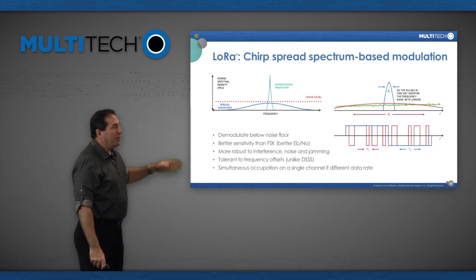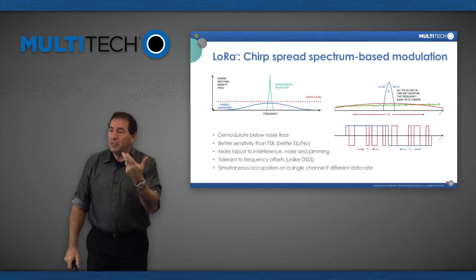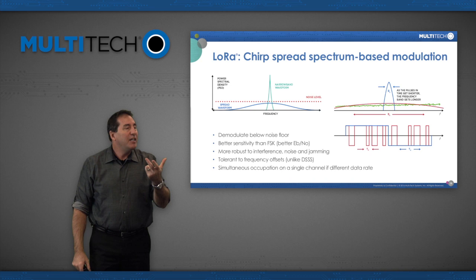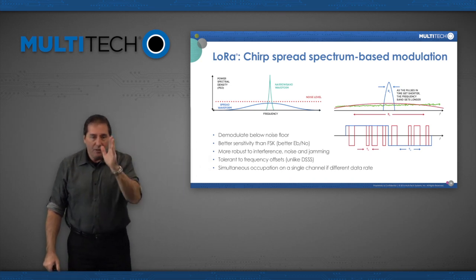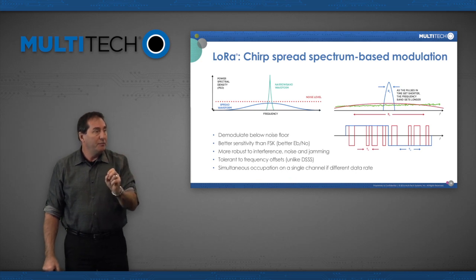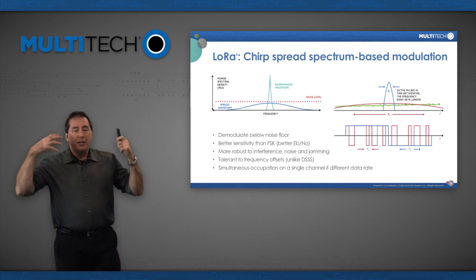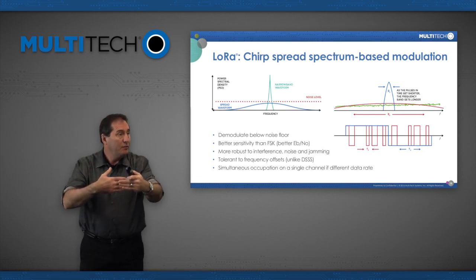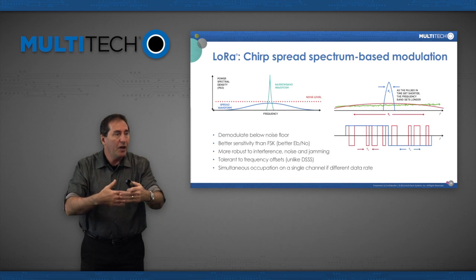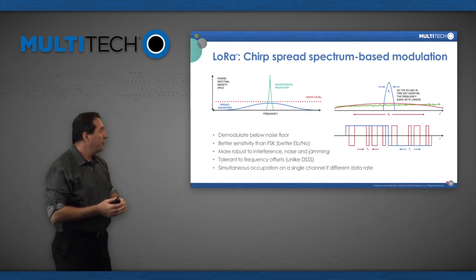Well, you have this Chirp thing, which is non-carrier wave based. What it does is it sends a preamble, the beginning of a packet that you can be listening for and then lock onto when you see it. So that's what the Chirp part is. You basically just start talking and you add some stuff on the front that allows a receiver to lock on and connect to you. So you don't have to be always locked onto each other.